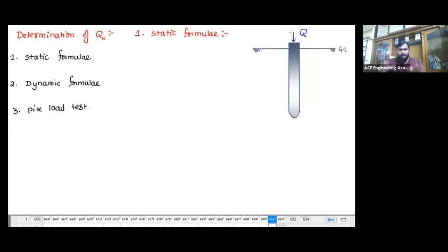So first you drive a pile or bore, whichever installation you prefer, and place the pile. Now I am going to construct the first floor. Due to that first floor, I am going to apply the vertical load. When a vertical load is applied on the pile, then slowly, first what will happen? Friction will develop due to the loading. First thing first, the pile will start to move downward. Yes or no? If you suddenly apply the load, the pile will start to move downward. When the pile starts to move downward, it will get resisted by the friction or shear developed between the pile and soil.